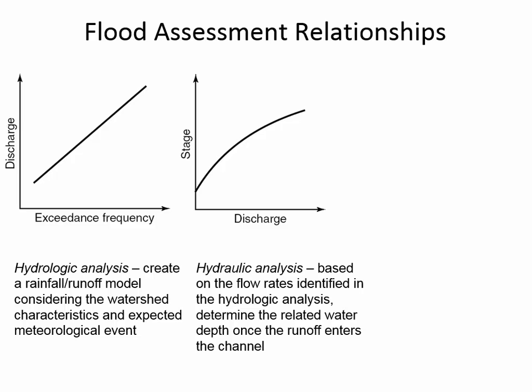You'd use Manning's equation. And you'd find out, for a certain channel width, B, and a certain side slope, 1 to T, you're going to try and find out what is the depth, Y. That's what the hydraulic designer is going to be doing.